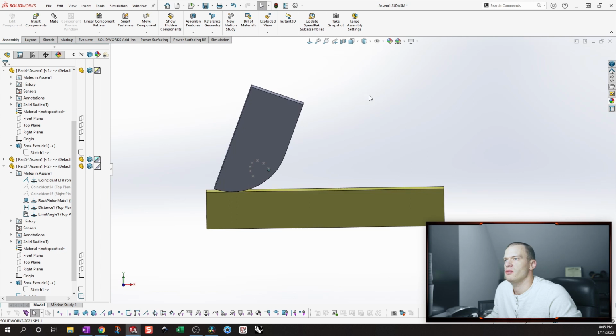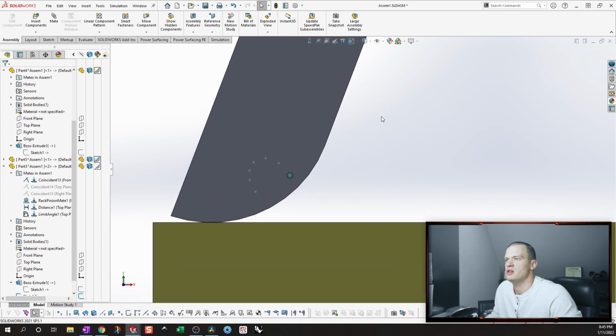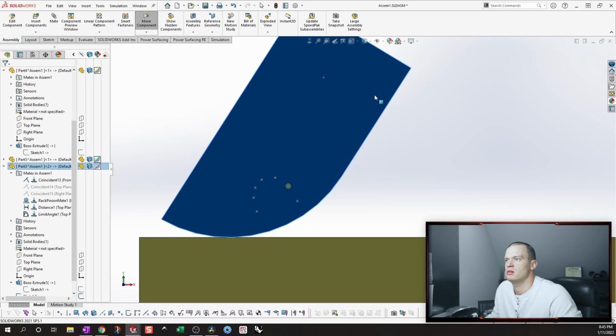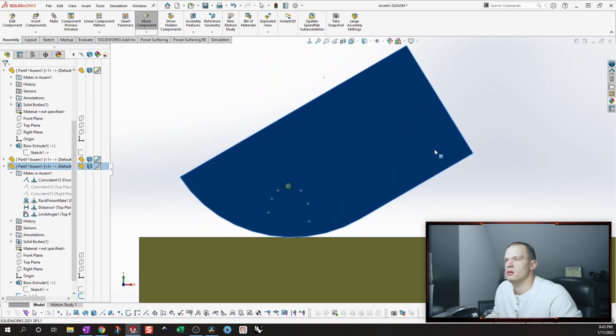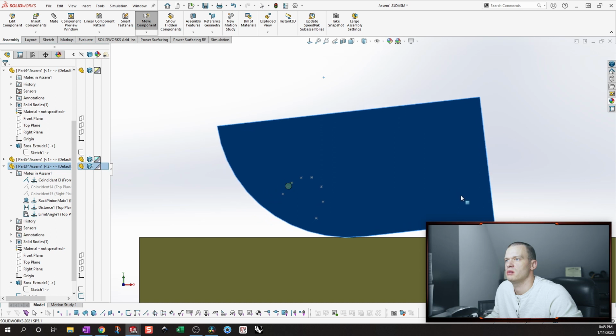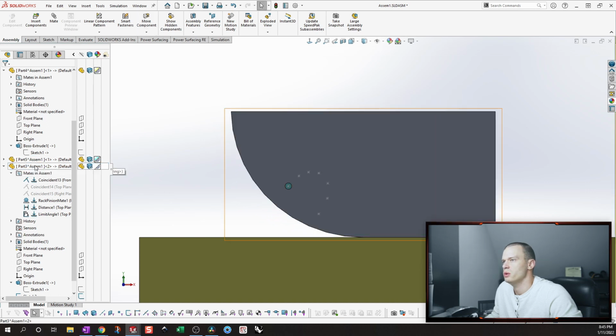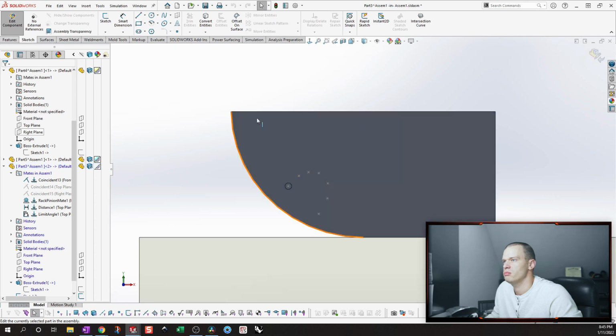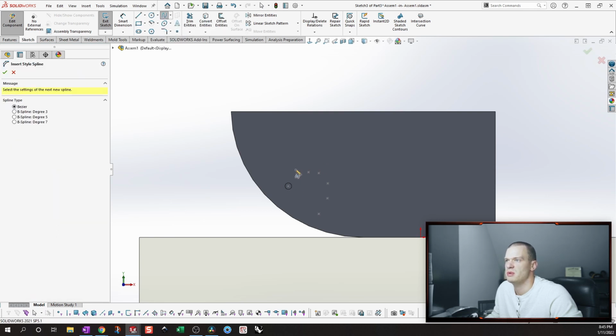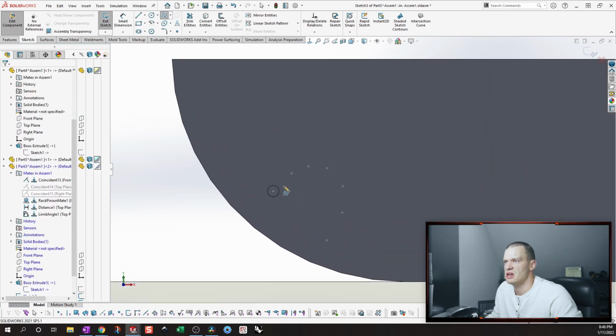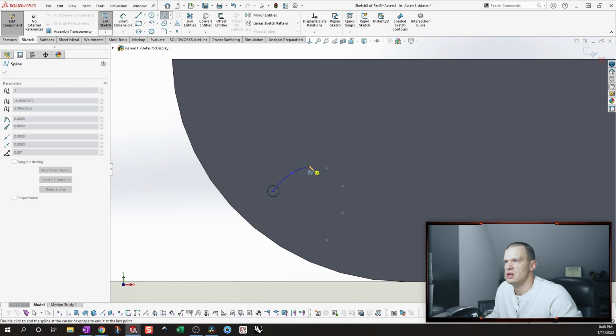All right, so now we have all of these points that, as we roll it through its motion, you can see they're describing where the pin path is. So it's really pretty straightforward. Now we have those points. We'll do it in a different sketch just so as not to mess up the points. And then we're just going to use a curve. Now you want to use a spline, not a style spline. I've tried both. You could use a style spline and just add a whole bunch of points, but it's essentially the same as using a spline in this case. And we just trace this out.